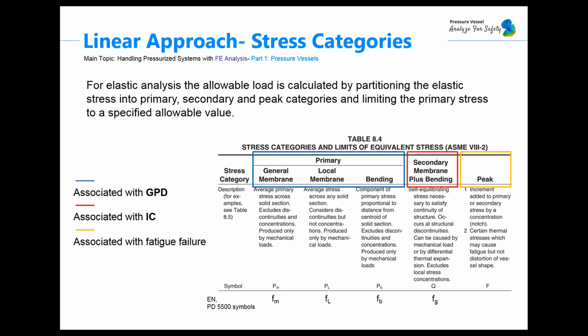So general primary membrane stresses are self-explanatory. They are membrane stresses with the characteristics of primary general stresses. It's very easy, and these are found remote from large discontinuities. So these are found far from large discontinuities like cone-cylinder intersections and nozzles. Examples of general primary membrane stresses are membrane stresses at the center of a flathead, or circumferential and longitudinal stresses within a pressure vessel.